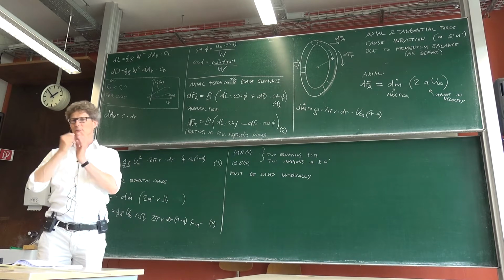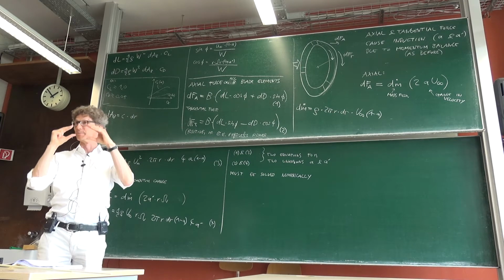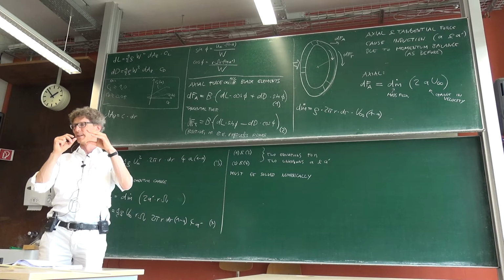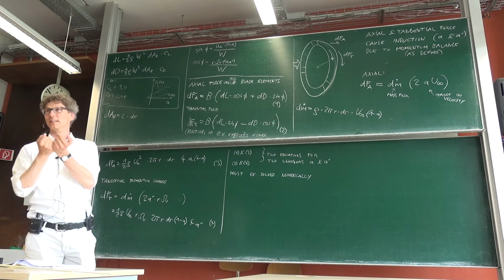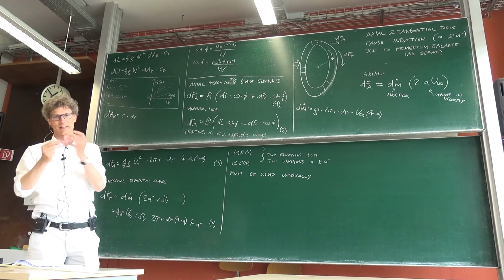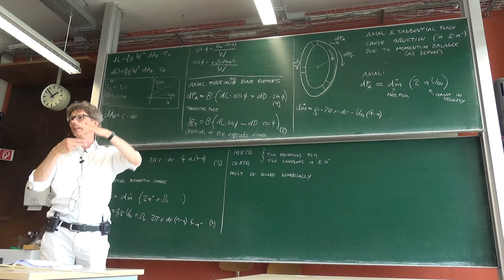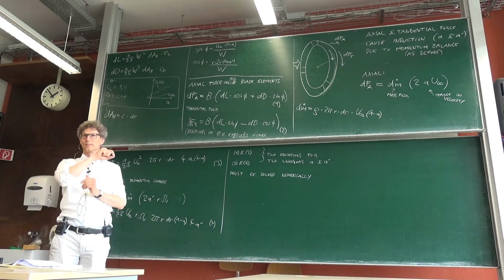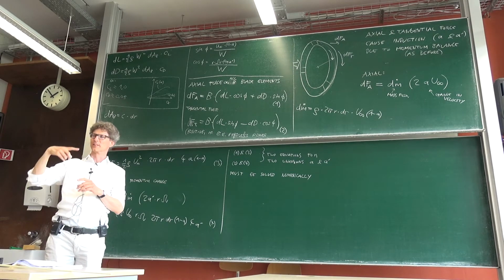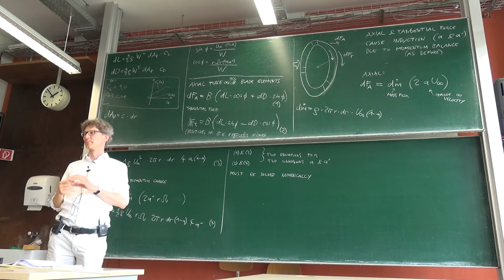You assume that you want to operate your wing with the best angle of attack, where you get a specific fixed lift and fixed drag coefficient. And then you basically fix the lift and drag coefficients. With these assumed fixed, and the angle beta chosen later so that it will always lead to this angle of attack, you can resolve these equations a bit, not easier, you still need to resolve them, and then afterwards you can find out the angle beta that would be the right angle for your wind turbine.